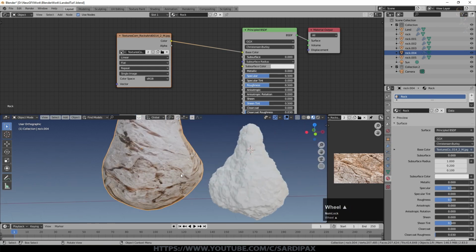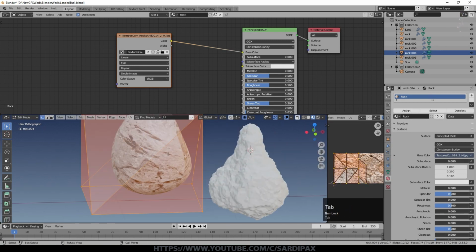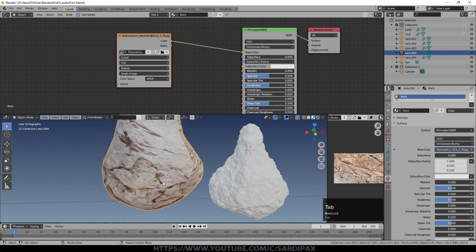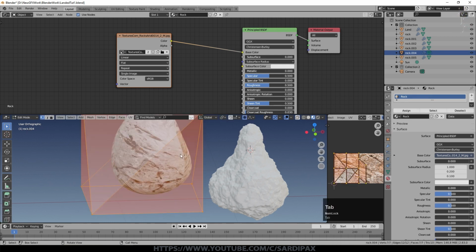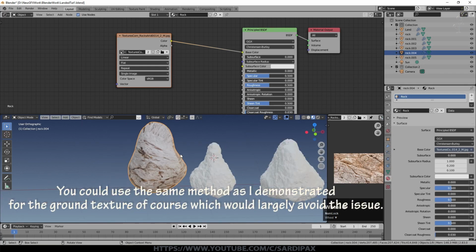As I said, if you really want to take the time, you can properly UV unwrap it by adding a seam. But bear in mind, when you do that, you are going to have a seam. And so there will be occasions when even that seam is visible. With shapes like this, it's quite difficult to have a completely seam-free unwrap.